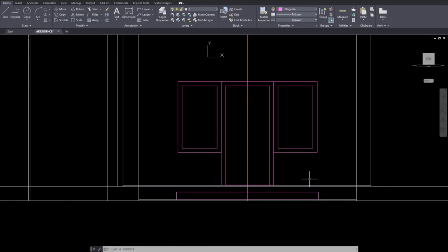So it's one step above the street level, and then the building floor is one step above the stoop. So you have at least 2 steps difference between inside the house and outside the house. And why do we have to have that? When there's water, rain, snow outside, we want to keep the inside above the water level. If there is so much rain and snow, you want the house to stay dry and clean, and that's why we always raise the floor, normally way above the street level.